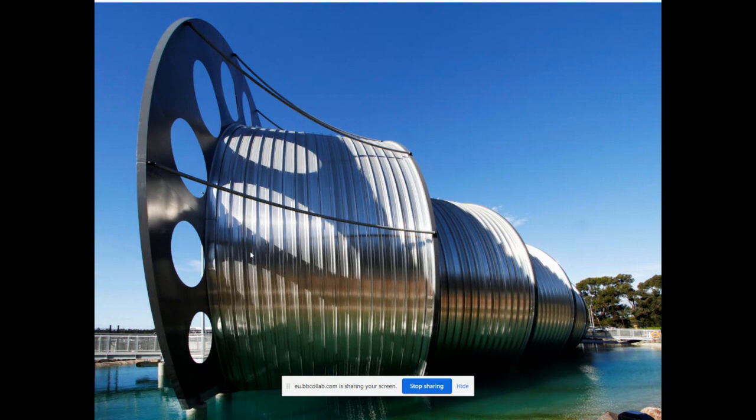Now, the idea of it was that there's a pipe on the top of the building that circulates water to run over the surface of the aluminium and into the lake. And the idea is that at night, with these clear skies in this part of Australia, you get a huge amount of back radiation. So that water cools just by back radiation. You don't do it during the day because you get too much evaporation. And the water is very expensive, so you don't want to lose it. So it's done at night, and it's cooled at night.